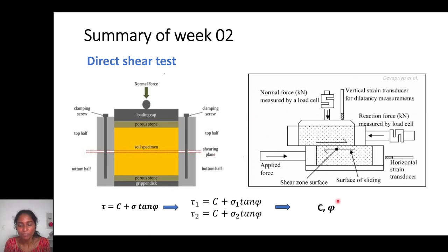So what is the purpose of direct shear test? If somebody has given a soil, and you want to determine the cohesion and angle of internal friction, we need to conduct some test so that it will give these two, because for any two to three multiple soils, if you have these parameters, you can actually tell what is the corresponding shear strength.